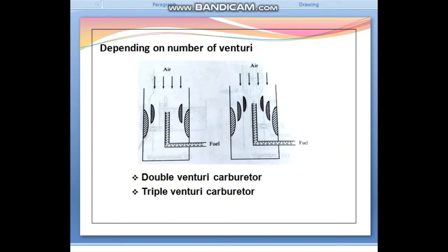Number two is that an annular blanket of air is formed. The blanket keeps the fuel off the walls of the induction tract. Number three is that more efficient mixing of air and fuel is obtained without an unacceptable reduction in volumetric efficiency. The volumetric efficiency reduces only slightly since only a portion of the incoming air is subjected to the increased pressure drop.